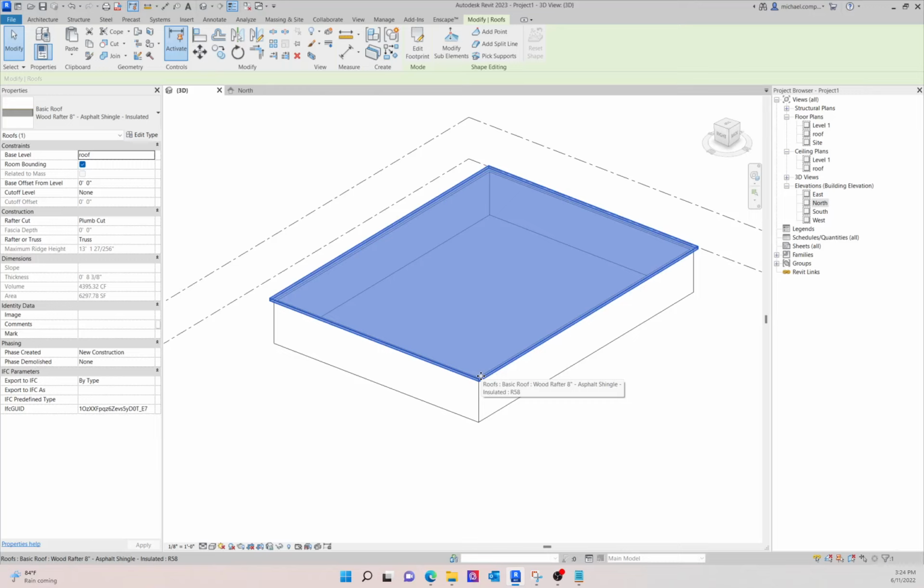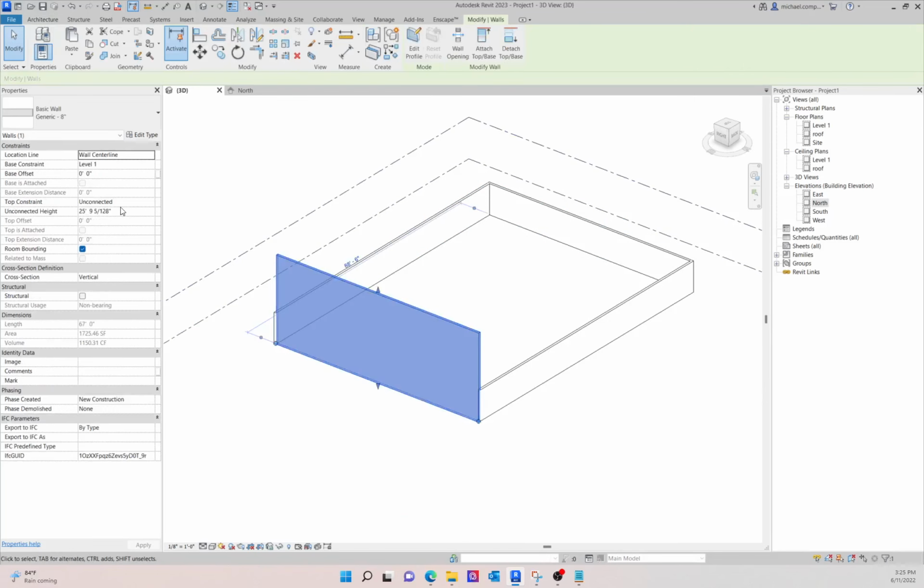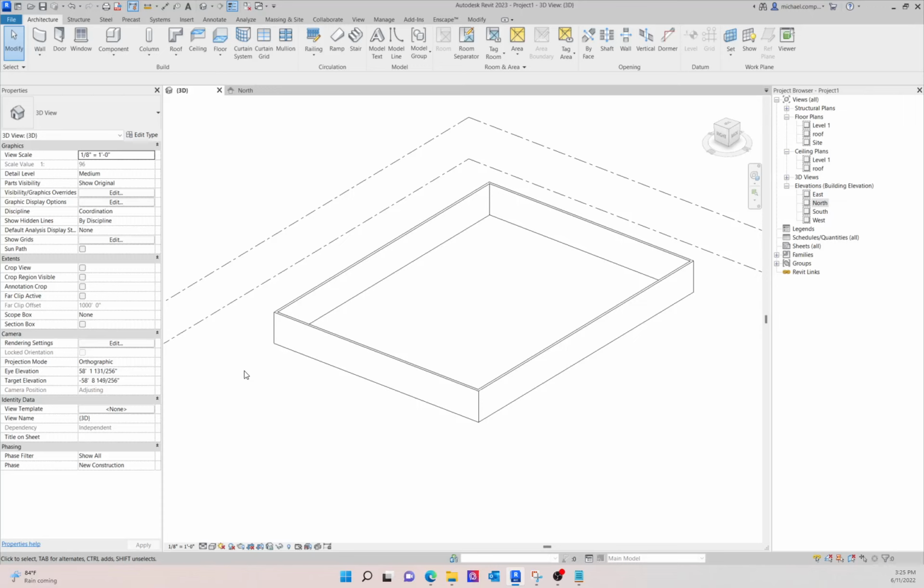Most of the roofs that we have, or at least most of the roofs I design, are terminated at the end of the wall. So they're inside the walls. But I thought this would be a helpful explanation to understand how the roof command works by footprint. So I'm going to delete that particular roof. I'm going to change this guy back to 9 feet, which is what it's supposed to be, and then call that a day. The other one I was going to show you is roof by extrusion, excuse me.